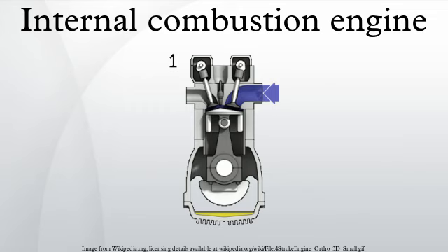Carbon fuels contain sulfur and impurities that eventually produce sulfur monoxides and sulfur dioxide in the exhaust, which promotes acid rain. In the United States, nitrogen oxides, PM, carbon monoxide, sulfur dioxide, and ozone are regulated as criteria air pollutants under the Clean Air Act to levels where human health and welfare are protected. Other pollutants, such as benzene and 1,3-butadiene, are regulated as hazardous air pollutants whose emissions must be lowered as much as possible depending on technological and practical considerations.